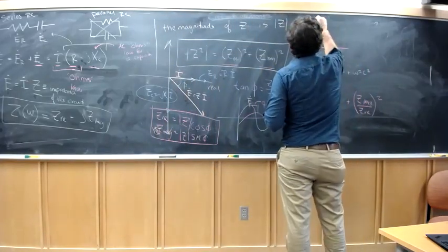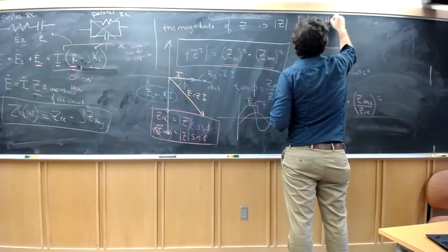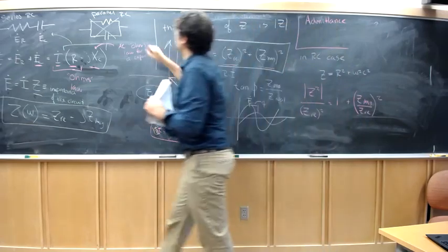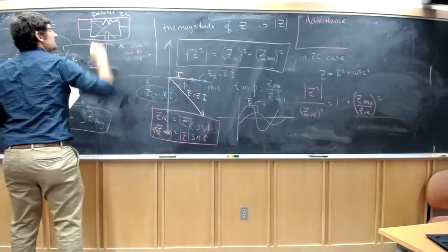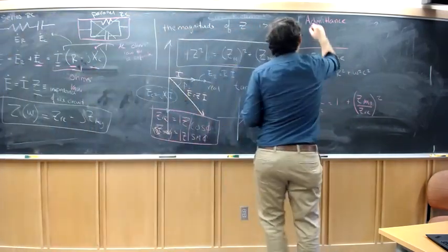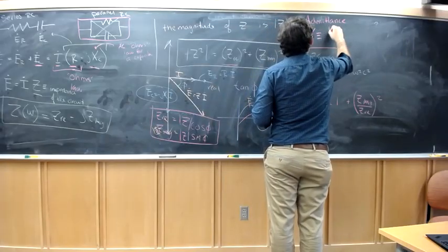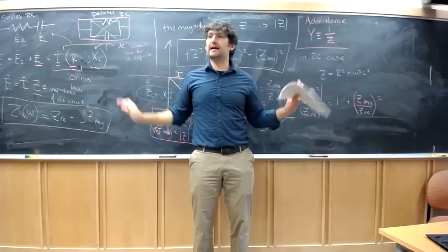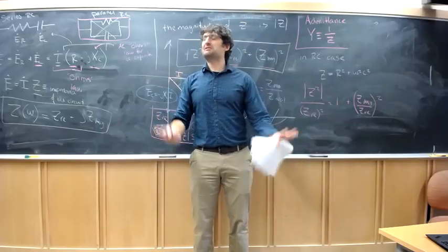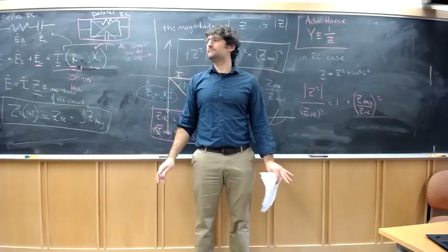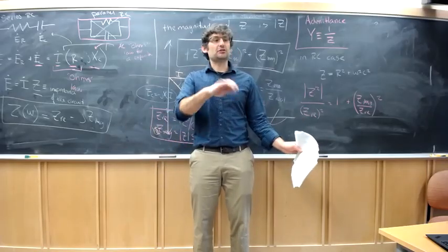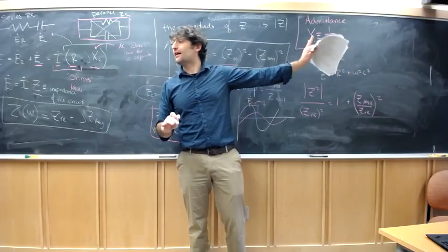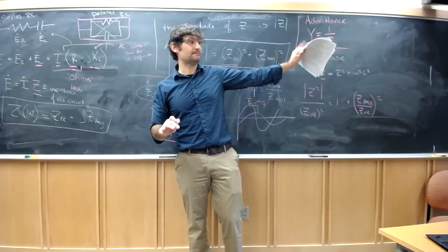You'll use something called admittance. And this just simplifies the math in certain cases. Like when you're talking about parallel RC circuits, it's easier to use admittance. And we call that Y. It's just defined as 1 over Z. But it's the same. Everything's kind of exactly the same. It's just 1 over Z. It just makes the math a little easier when you're talking about parallel circuits. And sometimes you can tell your frequency response analyzers to measure admittance. And then it will give you this value in inverse terms.